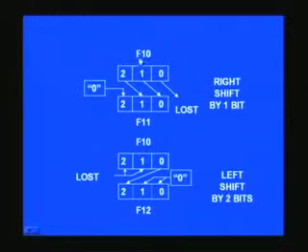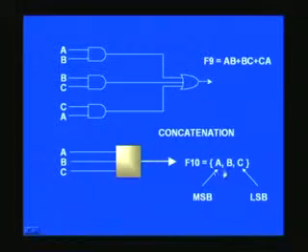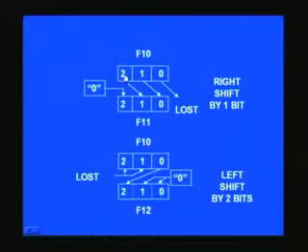When you shift, let us say we have a signal which is 3 bits wide. In fact, this F10, if you notice, it was derived from concatenating 3 signals as such. So after right shift, what happens is, these are all the weights, you know, that 8421 codes. So probably I should have put it right on the top. This is not a data as such. It's a bit position that I have referred here. And once you right shift this one, what you are going to do is just shift it here. Then this 0 bit position, whatever data is in that position, it will get lost because we are not storing it. And if you want to store that, you can use some other Verilog statement to store in case the need arises. Otherwise, you don't really bother about that.